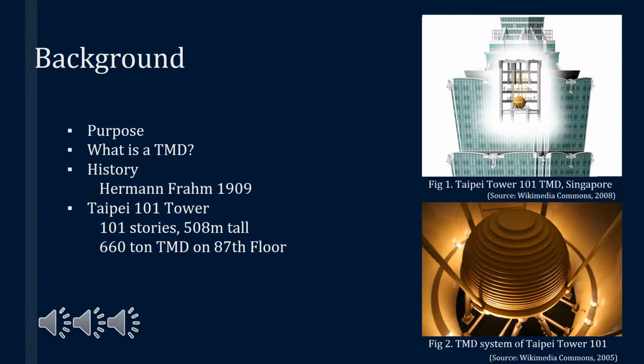The displacements and the accelerations can become very large, especially if the dynamic load frequency matches the structure's natural frequency, which results in resonance. Passive energy dissipative devices try to concentrate the dissipation of hysteretic energy in a few chosen and well-designed elements. The remaining portion of energy can be absorbed by the structure in elastic or near-elastic behavior.